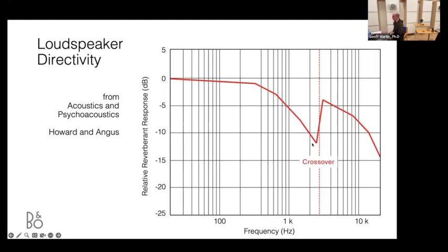less and less reverberant or reflected energy until you hit the crossover, where you go into a smaller driver, which becomes omnidirectional. So you get more reverberant energy or reflected energy again, and then that starts tailing off as the tweeter starts beaming. This is a natural behavior of a two-way system, if you've selected a crossover point where you've gone higher than a frequency where the woofer is going to be omnidirectional. So I'm assuming here that you've picked a crossover high enough that the woofer started beaming.